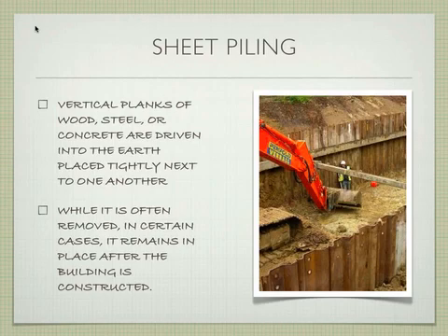We already talked about this. They're tightly next to one another. Most often than not, it's going to be removed after the fact. Sometimes they leave it in place. It's not going to be a stable enough material to attach to your building, but sometimes it'll remain in place as a retaining wall of some sort. So here's the example. We've slid all these pieces into the earth before we started digging. Then we bring our tractor in and we start digging in the middle.